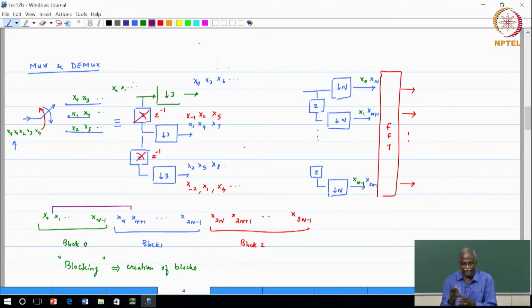If you wanted to have finer resolution of your data, for example, if you thought that your signal is not stationary, that your signal was quasi-stationary, that means things could change. So, between block 0 and block 1, something could have happened that you are trying to find out, those non-stationary elements, in which case you will do a sliding FFT, and that is equally permissible. Again, do we have a multirate structure for that? Yes, we do, but let me ask you to think about that.